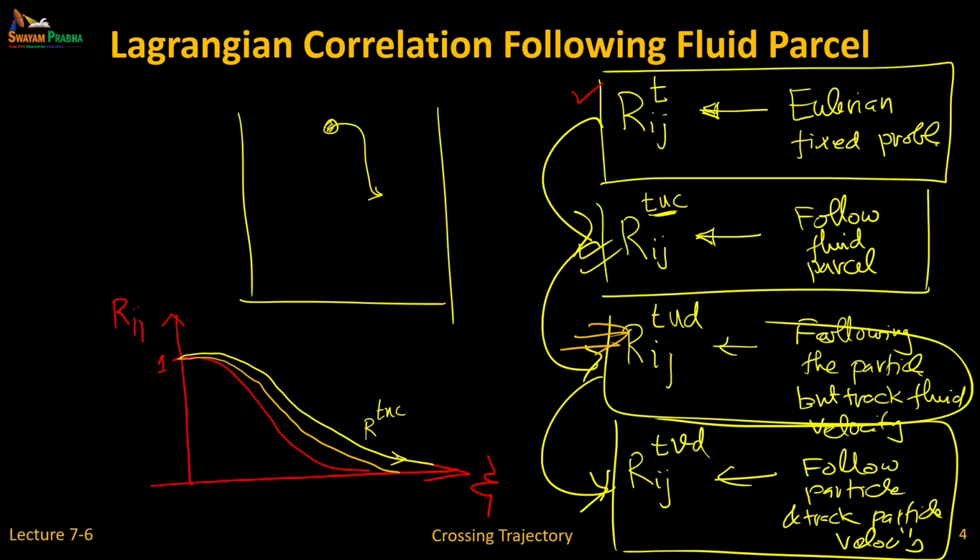And by the way, it can also be very large. So in other words, it depends on the Stokes number. For a small Stokes number, it is not quite following the fluid, it is cutting across eddies. On the other hand, if you think of a baseball, it may remember its velocity for a long time because it doesn't care about the fluid at all.